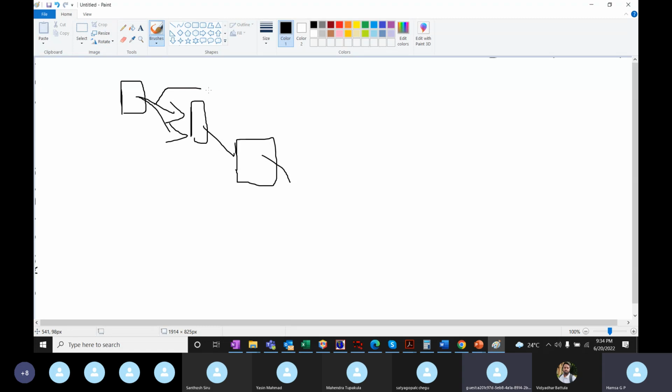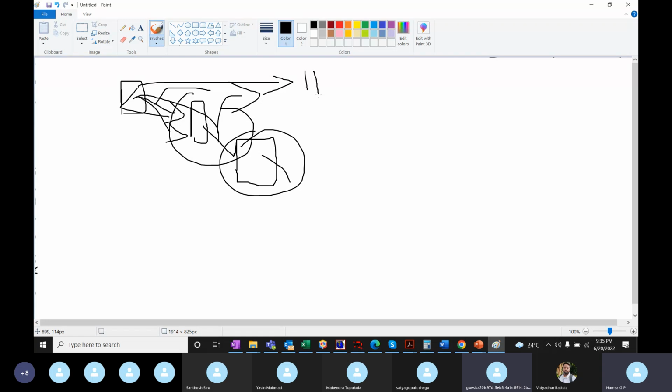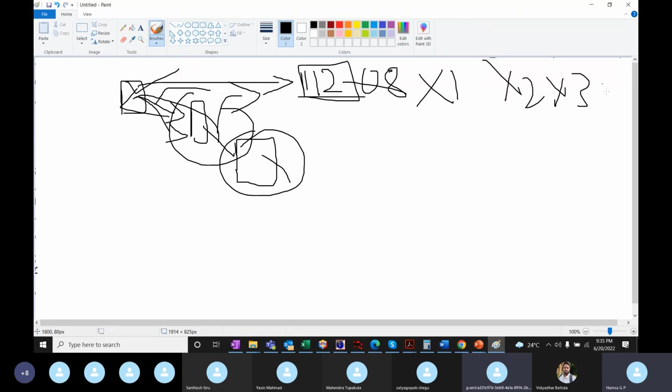So how is it sent? Through these messages. How does the ECU understand it is from the front sensor? Because it has an 11-bit identifier, which is 112. With 112 it understood it is from the front sensor. This sensor is sending some data with 8 bytes. And what is the data? X1, X2, X3, X4. This data, X1, X2, stands for there is an object.